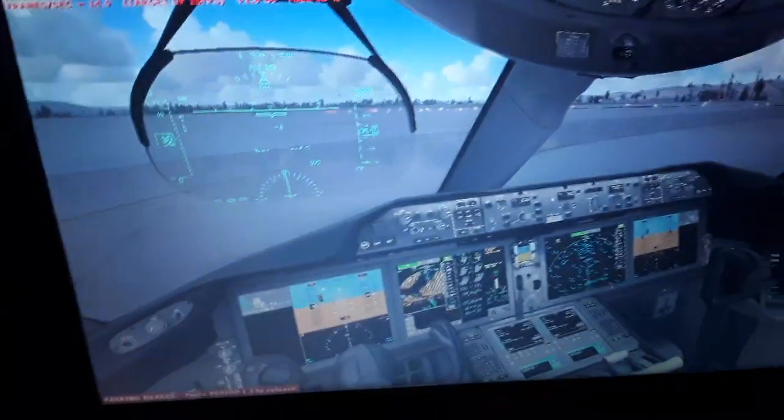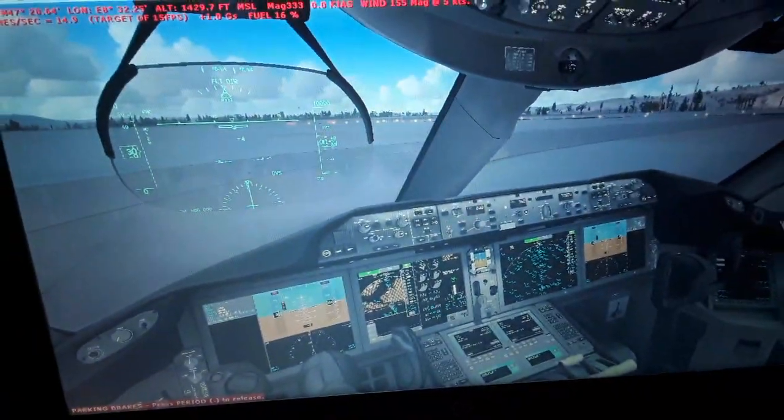We have also the ILS localizer crossbar. We have the flight director crossbar for manual guidance of the aircraft, and the autopilot crossbar for automatic guidance of the aircraft. The angle of attack of the aircraft as it flies in the flight mode, along with the autopilot and the auto throttle, and later the vertical navigation modes. We have also the side that displays the horizontal situation indicator, with the terrain, the magnetic heading and track, and also the integrated display of the flight plan.